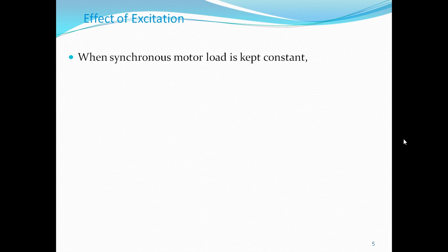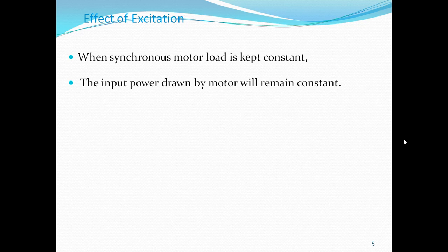When the synchronous motor load is kept constant, what happens? The input power drawn from the supply is constant. That is root 3 VL IL cos phi.